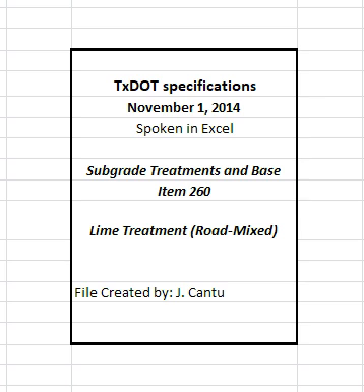When new base material is required to be mixed with existing base, deliver, place, and spread the new material in the required amount per station. Manipulate and thoroughly mix new base with existing material to provide a uniform mixture to the specified depth before shaping.